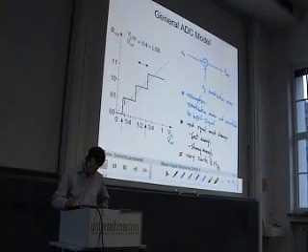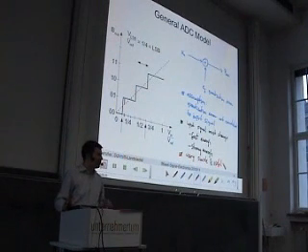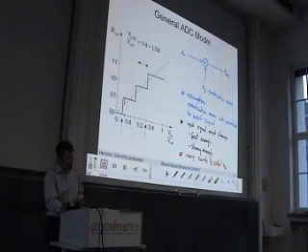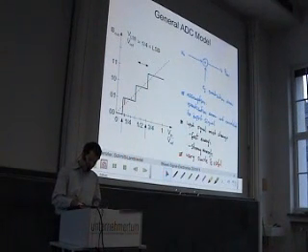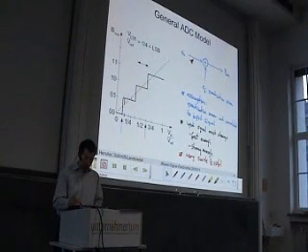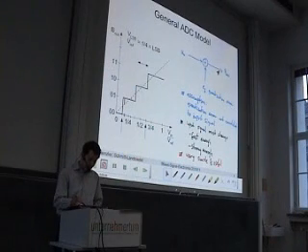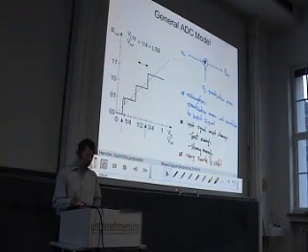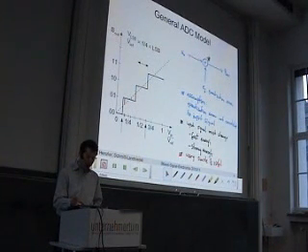And useful, especially for analyzing A to D converter architectures. However, you have to be careful, because here it looks as if we have only a basic adder. But look what we really add. We have here a voltage. Here we have a binary output word. So you have to be aware that this is only a model for a full A to D converter which does the translation from a voltage into a binary output word.